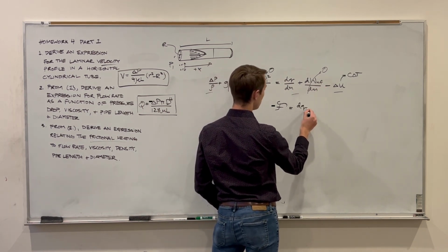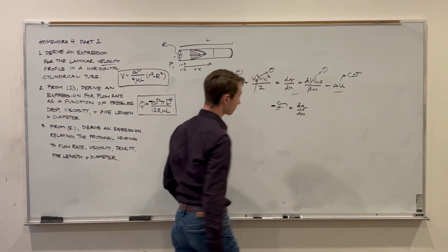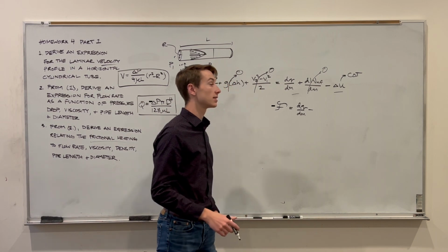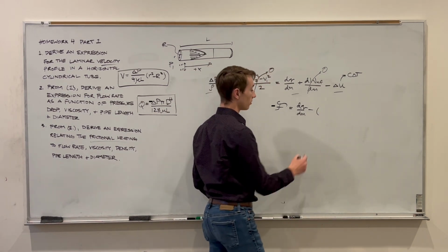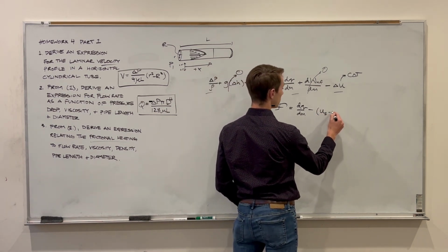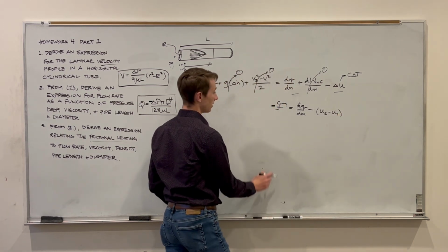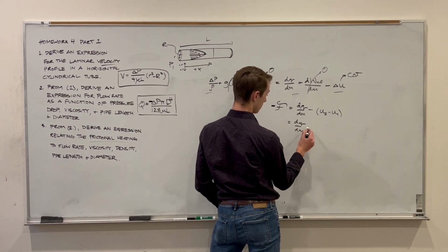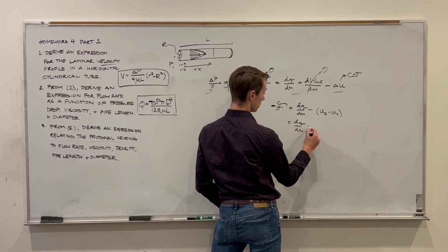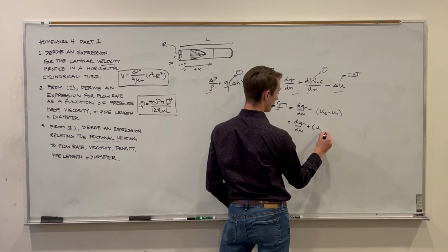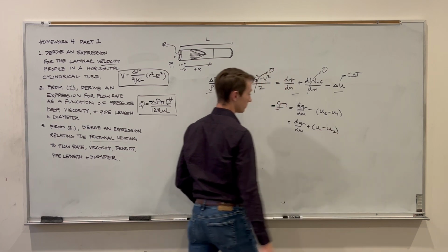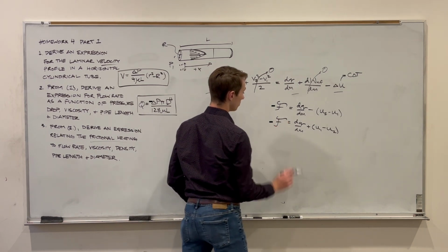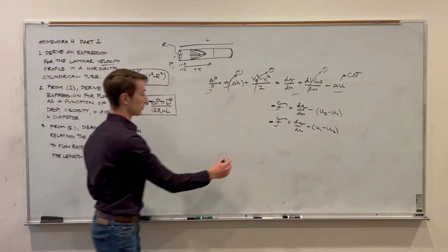So we have dQ/dm minus delta U. So delta U is going to be the change in internal energy, which is U2 minus U1. And then this can be rewritten as dQ/dm plus U1 minus U2. Okay, and this is what the frictional heating is defined as, right here.